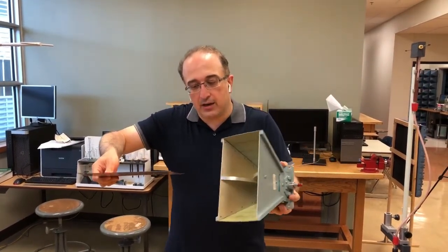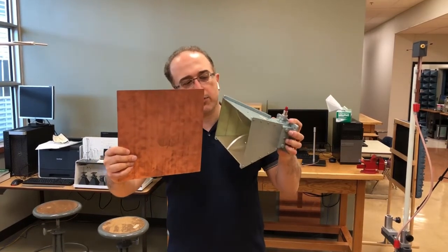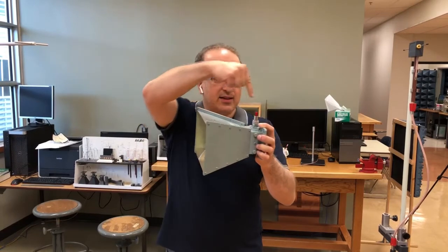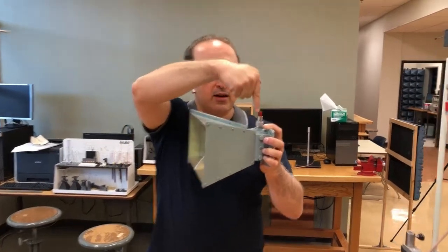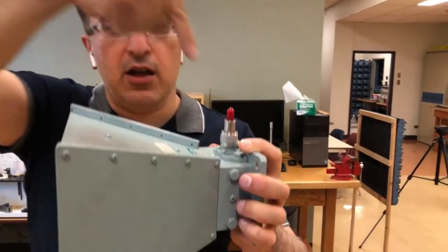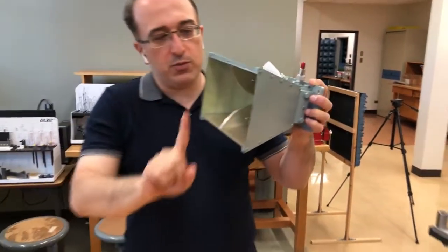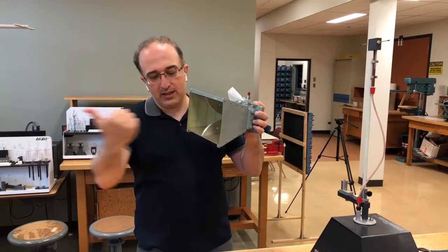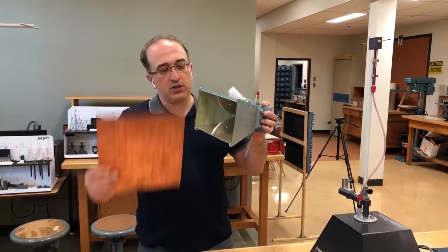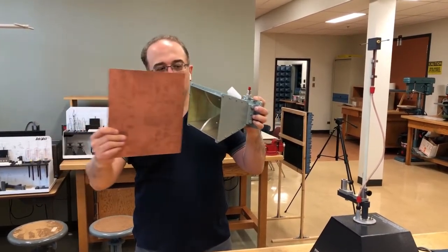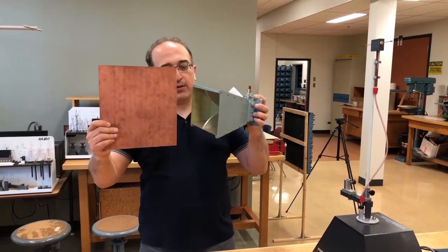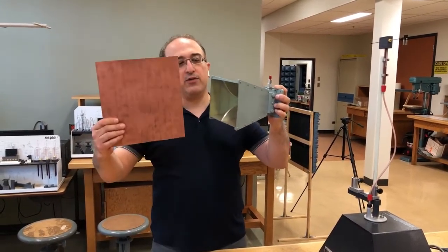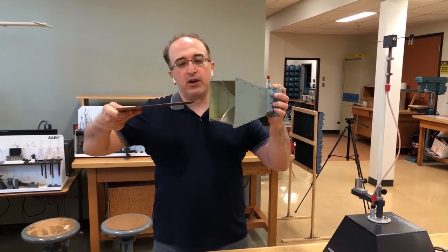So that's our E-plane. Sometimes it might be hard to identify the E-plane, but if you look at the feed point of the horn antenna, which is here, which is vertical, you can guess that that would be the direction of the electric field and the direction of maximum radiation. You know it from the course, so this would be essentially your E-plane. Now, the H-plane is, of course, perpendicular to the E-plane. So if that was my E-plane, this is my H-plane.